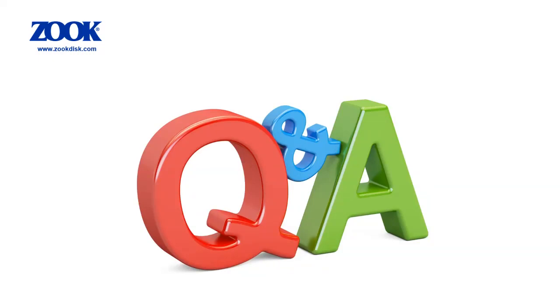Okay, very good. Thank you, Ben. Hot on the heels of that last question, the next one is, what does it mean when a disk is fail-safe? Okay, Ben here again. A fail-safe disk will burst at or below its rated burst pressure, even if it is damaged or incorrectly installed. That's the term used for fail-safe. This can include incorrect orientation of the disc relative to the flow direction also.